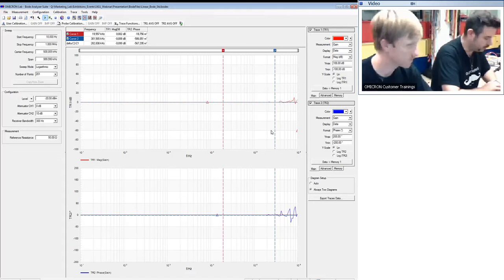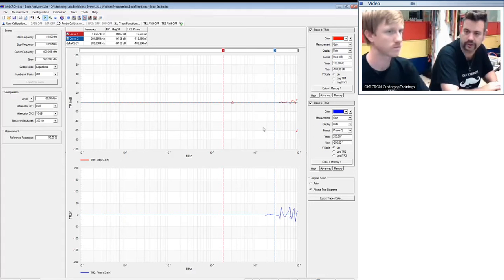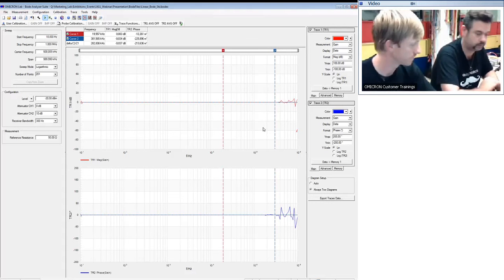Yeah, well, in fact, the switching frequency of the circuit is around 200 kilohertz. So above this, these are just distortions. And since we require a certain time to perform the measurement, this is a kind of noise that comes in. So there's nothing you can do against it, but you also can ignore it because it's above the switching frequency.